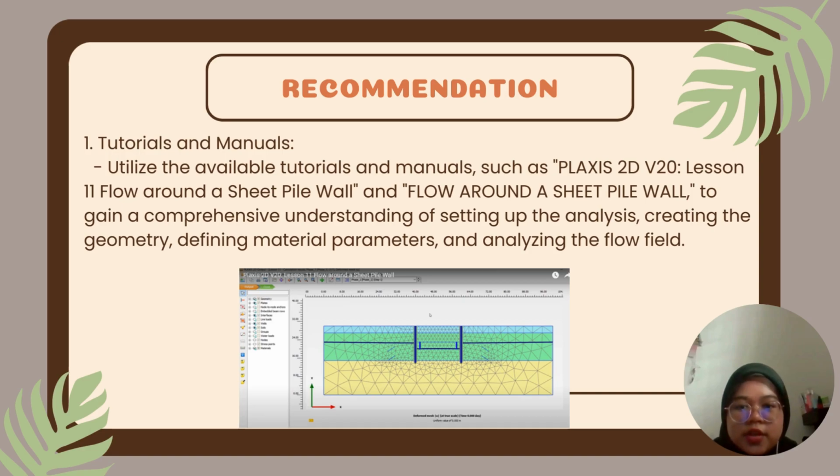So this is the recommendation for using Plaxis 2D software to see the flow around a sheet pile. We can utilize the available tutorials and manuals such as Plaxis 2D version 20 or flow around sheet pile walls to gain a comprehensive understanding of setting up the analysis, creating the geometry, and defining material parameters which analyze the flow field.